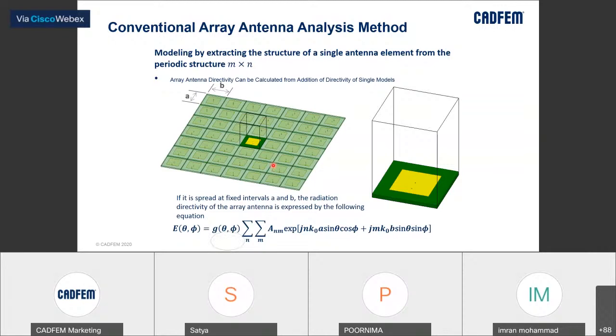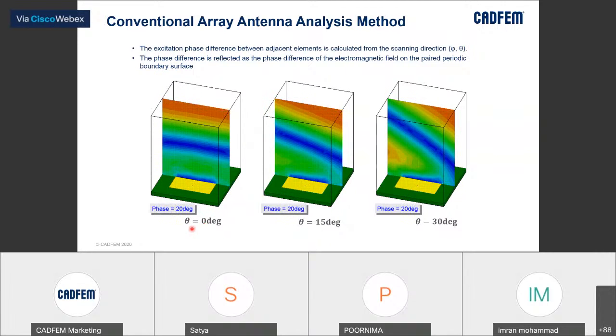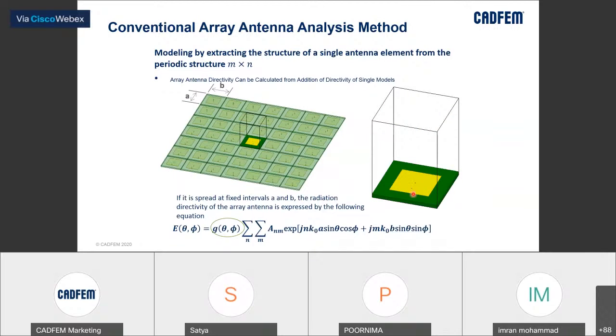And for that, the antenna array factor makes an important impact, depending on the single element behavior. You can see over here, suppose we are giving a 0 degree phase shift, in the sense that we are giving a 1 watt signal and a zero phase, because every signal will have a power component as well as a phase component.